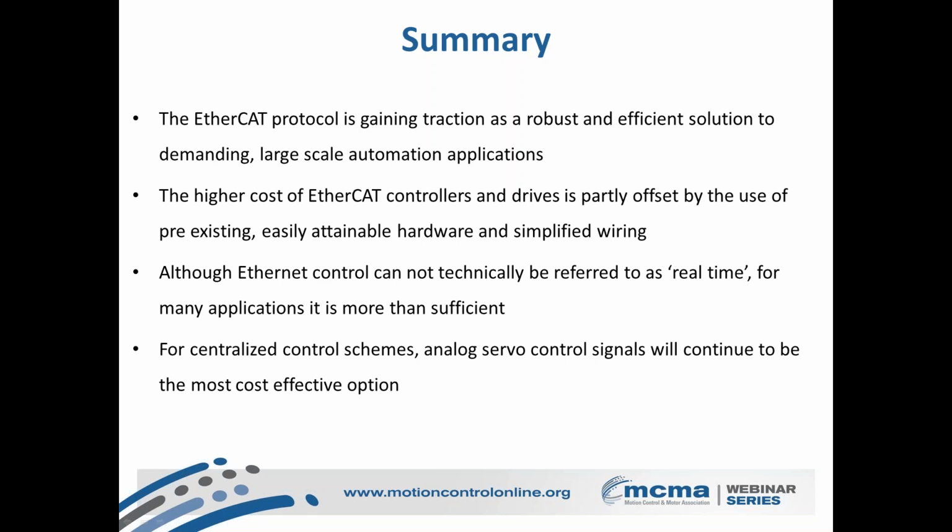For quite some time, the standard analog control signal with transconductance amplifiers and quadrature encoder feedback is going to be an industry standard, mainly because it's well understood, number one, and number two, it is going to be cheaper for quite some time. It'd be more cost effective. However, there are certain applications wherein the lower cost of those drives is going to be offset by the amount of trouble it takes to wire the system up and diagnose any potential noise on the system,